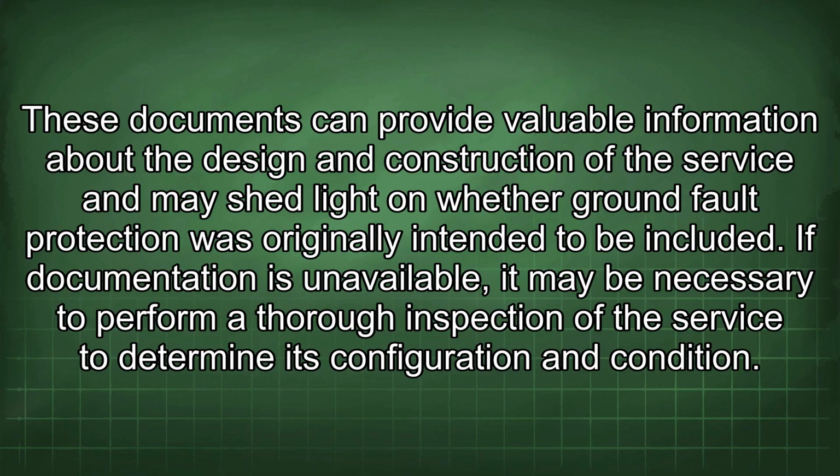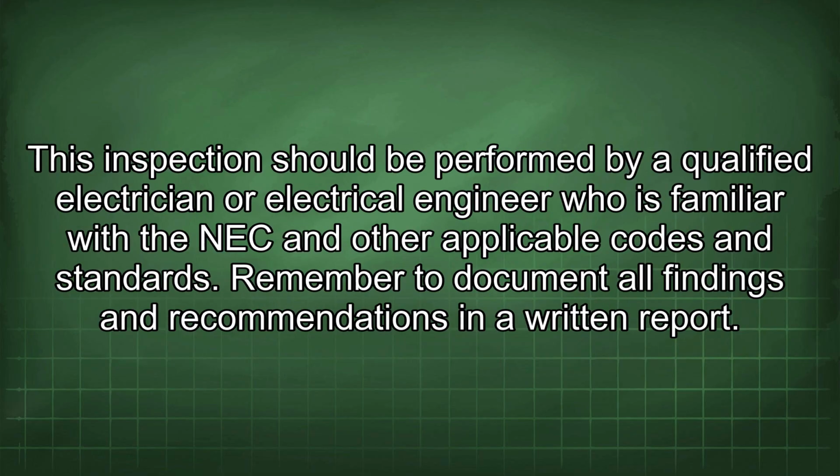If documentation is unavailable, it may be necessary to perform a thorough inspection of the service to determine its configuration and condition. This inspection should be performed by a qualified electrician or electrical engineer who is familiar with the NEC and other applicable codes and standards. Remember to document all findings and recommendations in a written report.